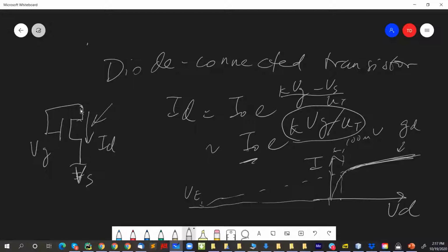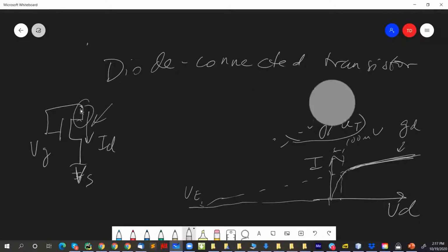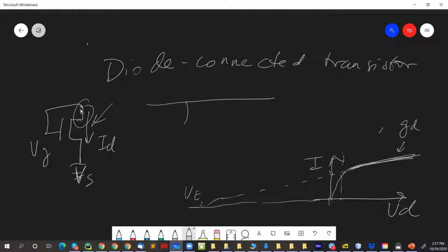Remember how there's a region around the drain end that's the depletion region? Maybe Shichi can draw it right around the drain. You can just circle it there. Right around the drain end of that transistor, there's a depletion region, right? And that's fixed size. So if you make the transistor longer, that depletion region as a fraction of the whole length becomes smaller and smaller. So the effect of that change on the overall length of the transistor, if you make the transistor really long, that little change in the depletion region width is going to get smaller and smaller as you make the transistor longer.